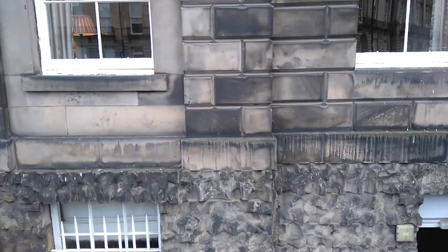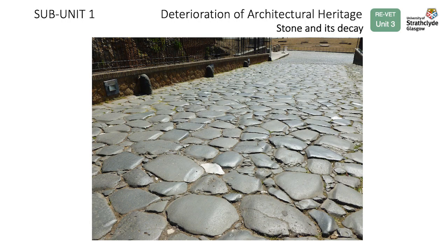Stone has been used as construction material since prehistoric and ancient times, and thereafter, researching its mechanism of decay and conservation is vital. The change from rock to cut stone is a substantial one, and it makes the stone, especially its exposed surfaces, very vulnerable to the new environment, and a suitable place for living organisms to develop. This is why the process of stone selection, cutting and finishing is very important for the durability of the stone.